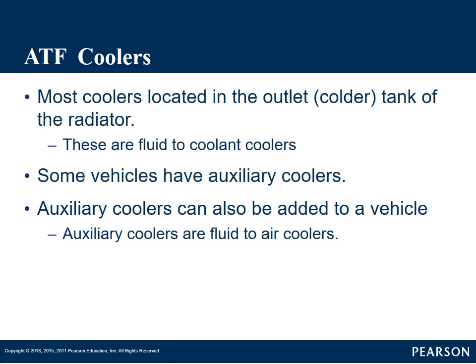They do that especially for colder climates, because in colder climates we want to get that transmission up to temperature. We don't want it to run at 50 degrees. We still want to get it up in temperature. So it'll cool it pretty good in the auxiliary coolers, because we don't have hot coolant running over these auxiliary coolers. We run it through the auxiliary coolers, through the radiator, it warms it up. But when everything's warmed up and hot, it helps keep that fluid cooler before it gets back to the tank.